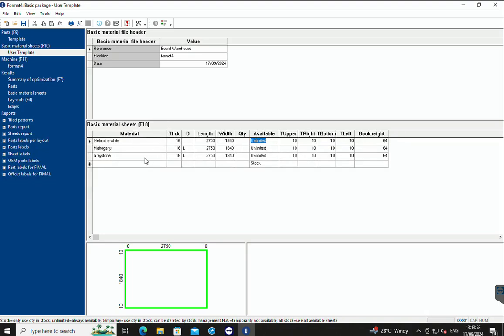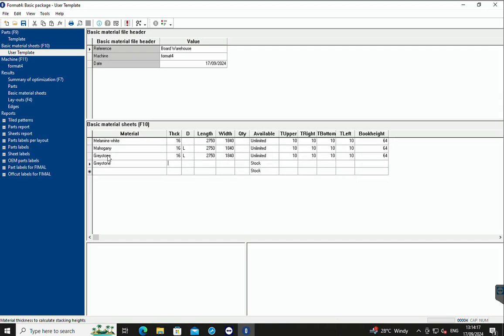Then to add a new board, you type on the last one, just click on it, and say enter. Enter, enter, enter, enter. What this basically does is copy all the fields. If you go to the next field, the new blank one, and say enter, Ardis will copy that whole line, and you can just say enter again throughout all the fields, because all your fields are mostly the same.